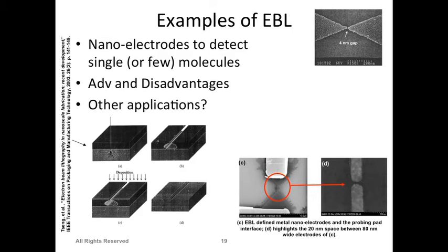Okay, and that has been shared with the E-beam lithography, and also with the ion beam. So in the paper which I shared with you for the nanobore fabrication and shrinking, we were actually using ion beam, if you read the paper, to drill holes. In that case, we were not doing the lithography, because ion beam is used for many different purposes. It's also used to etch certain materials. Let's say if you use an ion, a certain material, you focus it and choose a specific energy, you can actually erode or etch away certain material because of the ion bombardment. So they will not penetrate, but you can remove the material.